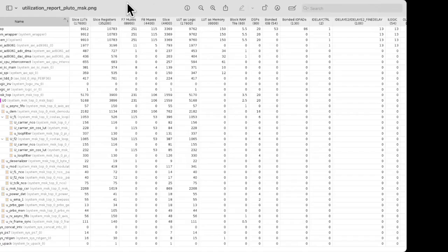Another good thing that we found is that yes, our FIFOs, the first in, first out buffers for both receive and transmit, and also the circular buffer for the synchronization word search, are successfully being assigned to BRAM. So they're not consuming the lookup tables, which are in short supply, the thing that you want to only spend when you have to. And the block RAM is being consumed successfully.